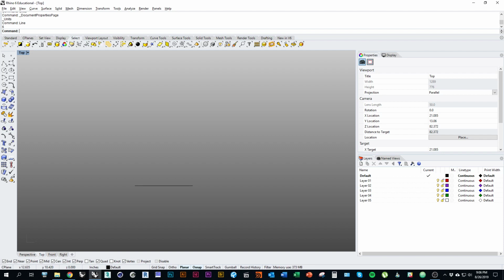If you look at the pictures on the assignment sheet, you'll see what I mean by the edges. So I'm going to use the command arc. Type in arc. Now, like with any command in Rhino, whenever you enter it, you'll see that there are a few options for how you can draw with it. In this case, we're going to use the option for tangent. And what that will allow us to do is snap to our existing line and make sure that whatever arc we draw, it's coming off the end of that line tangent so that it forms a kind of continuous curve.